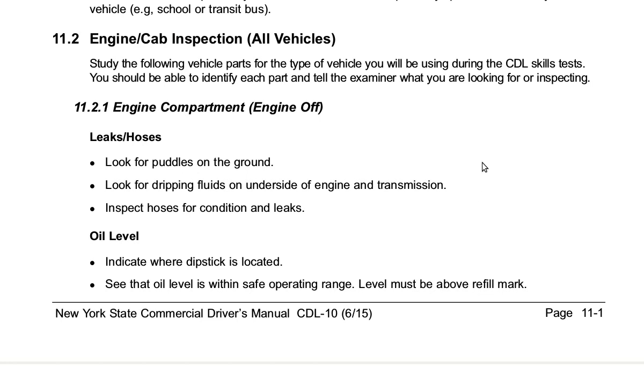Engine cab inspection, all vehicles. Study the following vehicle parts for the type of vehicle you will be using during the CDL skills test. You should be able to identify each part and tell the examiner what you are looking for or inspecting. Engine compartment, engine off. Leaks, hoses. Look for puddles on the ground. Look for dripping fluids on the underside of the engine and transmission. Inspect hoses for condition and leaks.